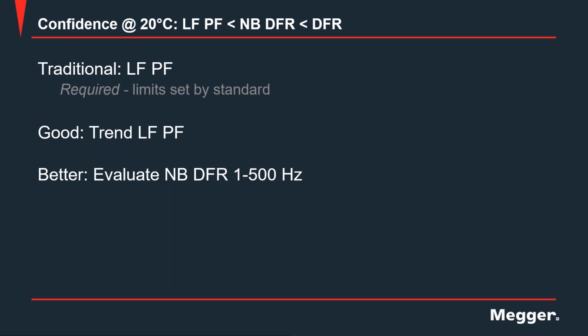You know, sometimes people will say, well, I would expect to have a higher power factor at higher temperatures. And maybe the dielectric response will tell them that that is not the truth for that specific type of insulation. So things will change. You have aging processes. You may have a fault in the system that will change the condition of the insulation. There are many things that will happen during the service life of the equipment.